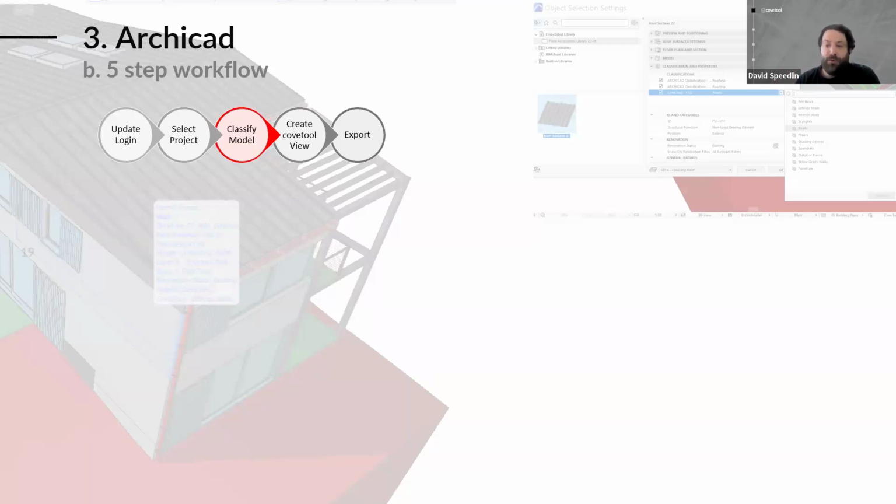The categories are roofs, floors, and exterior walls, etc., much like the other plugins. This can take a few seconds depending on the complexity of the project. Some elements may not be classified if the plugin did not identify any geometry with the correct position ID and properties. So you want to make sure that you've checked all of the elements and that they're in the right category.